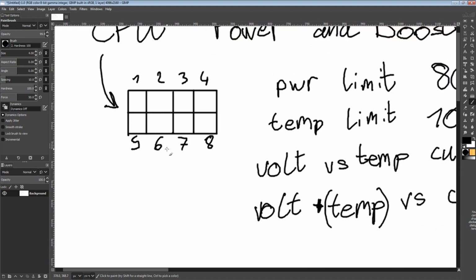Because the other thing to keep in mind, especially with Ryzen CPUs, is they have a lot of temperature sensors built into the die, but when you're checking the CPU temperature, it'll only ever give you the temperature reading for the hottest core. So if you're smashing power into Core 1 because the boost algorithm is doing its thing, Core 1 is going to be reading like 70 degrees or something, right? And that's pretty disconcerting when you're just watching a YouTube video or something, but the rest of the chip is well below 70, right?